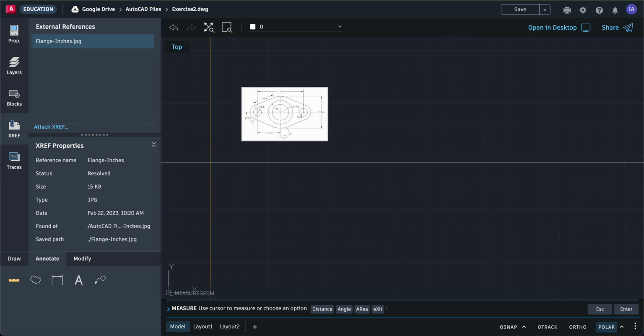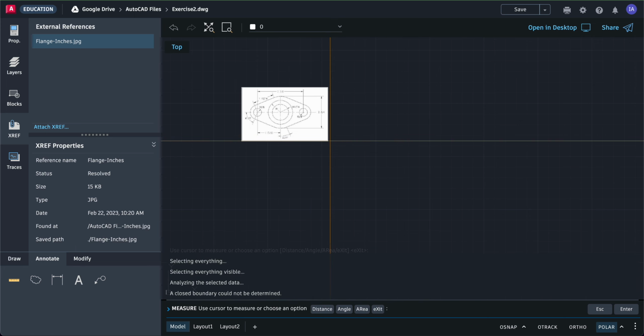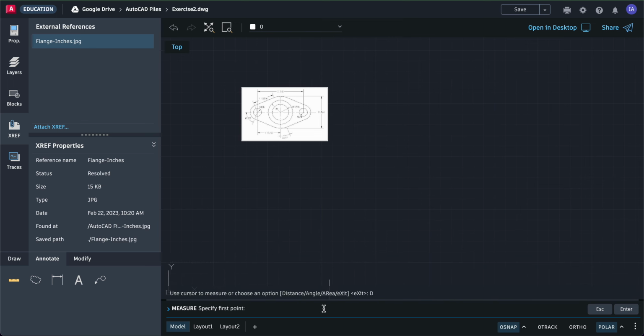You click measure, and then you click at the endpoint here. OSNAP is not turned on, so turn it on. And then click on that endpoint up to this endpoint. It's not on again. OSNAP is on, so endpoint, and then you click distance. Oh, it didn't work. So click endpoint and then click endpoint, and then you see that it's 4 inches.